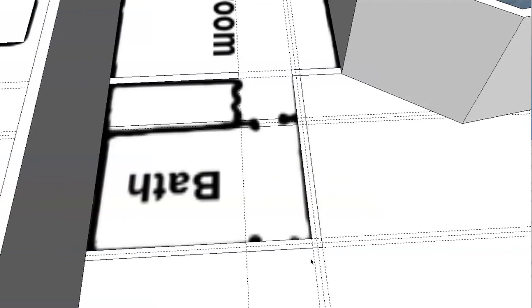All right, now you can see one thing that I did here in the floor plan. It looks like there might be stretches of wall that kind of poke out on either side here. But in a floor plan, that actually means there's going to be a door there. Now, a door on a floor plan, you want to specify that there's going to be an opening there. But in the case of a SketchUp model, a door is just a hole that you punch in a wall. So you do actually want a wall there. So we're going to go ahead and make those solid walls, and then once we go through and add the doors and the windows and things like that, we'll know to punch a hole in that wall for the door.